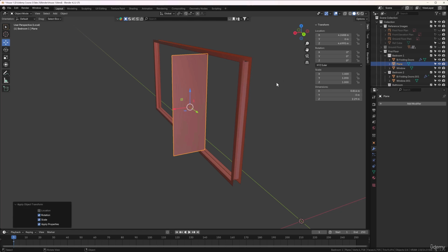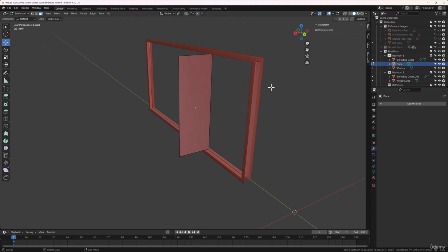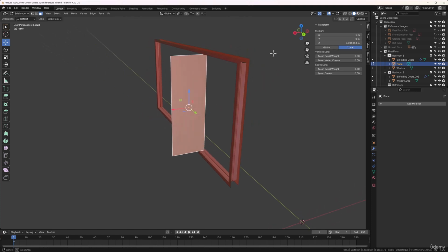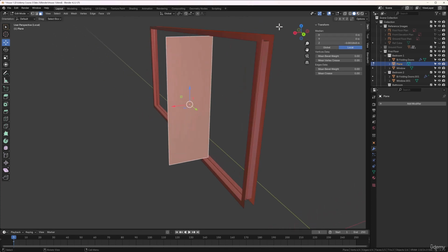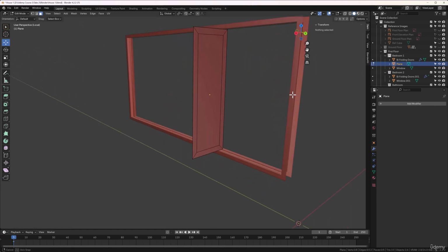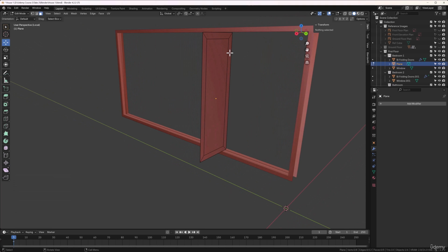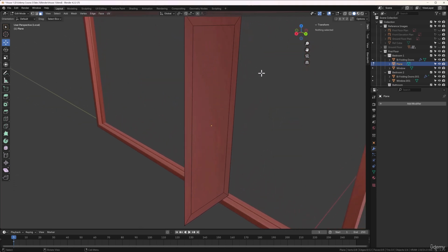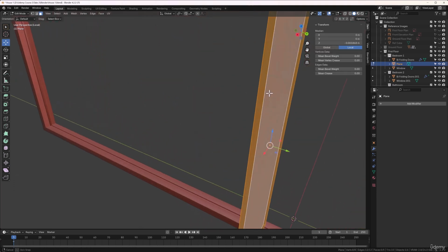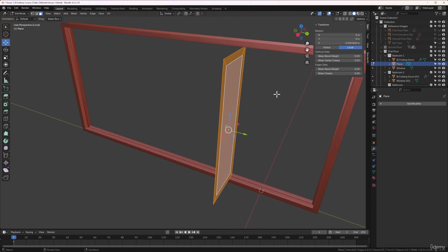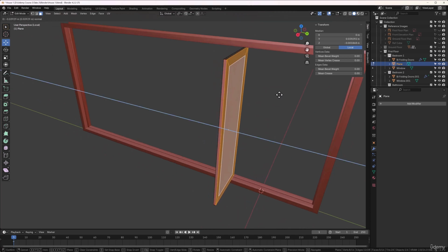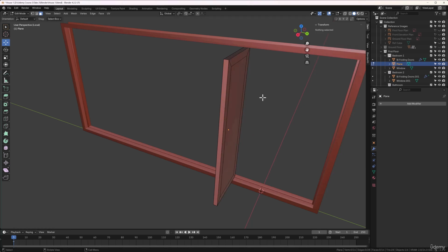So let's tap into edit mode with that, and let's select the face and let's inset. So let's press I and inset a frame. Oh, I'd say something like that should be good. And now that we've done that, let's press A for all, and let's go ahead and extrude that. So we'll press E and extrude this out nicely to get some thickness to this frame like that. And that's cool.